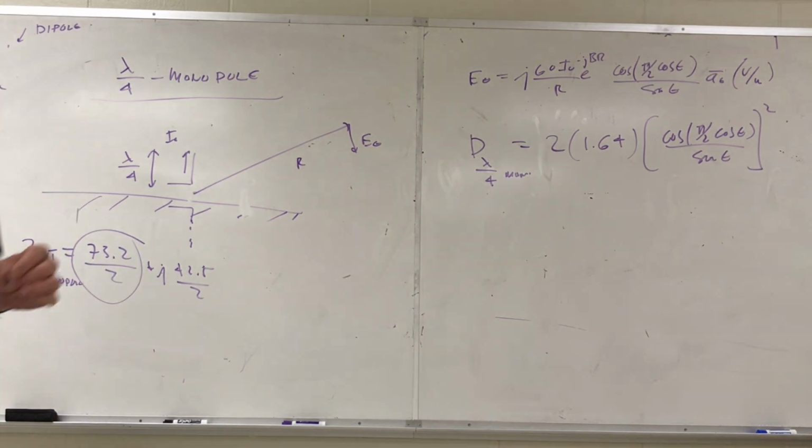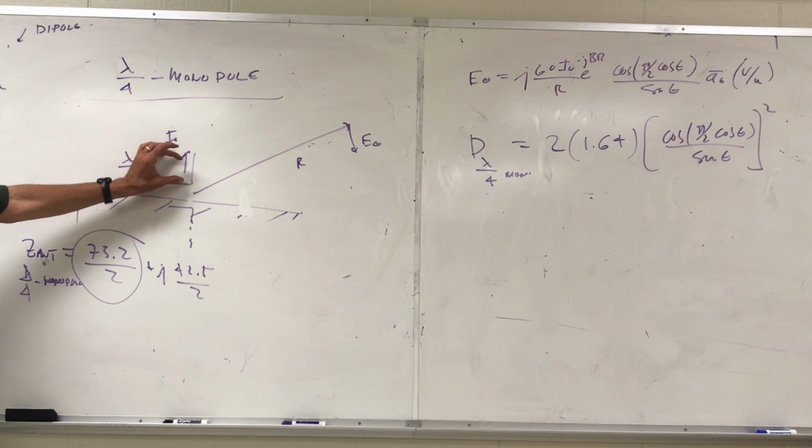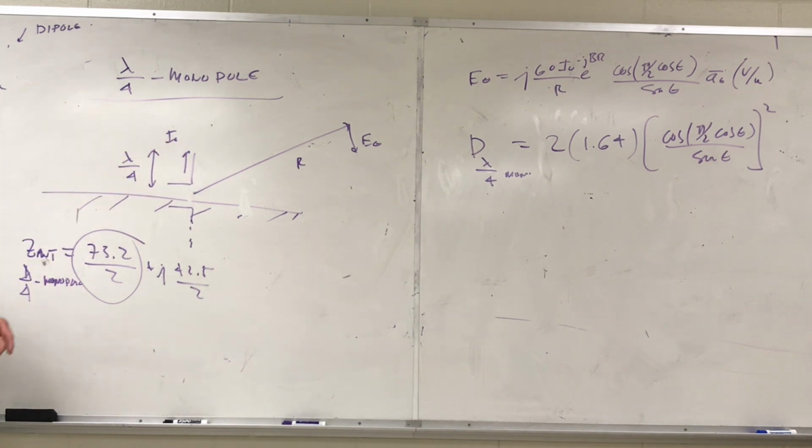Now if you cut that thing down, take 0.485 and divide it by 2, you get rid of the imaginary parts, just about 73 divided by 2, which is 36.5 ohms. With me, class? And it would be for a half-wave monopole.